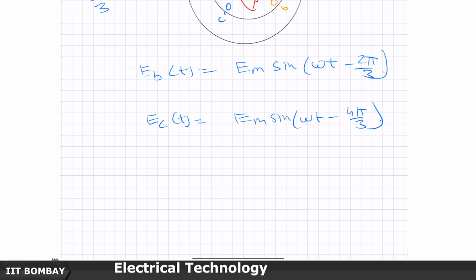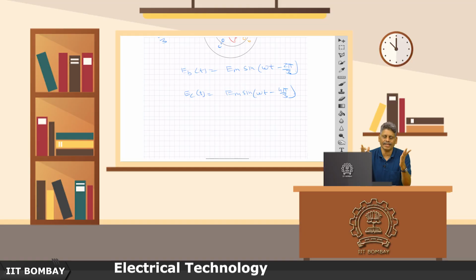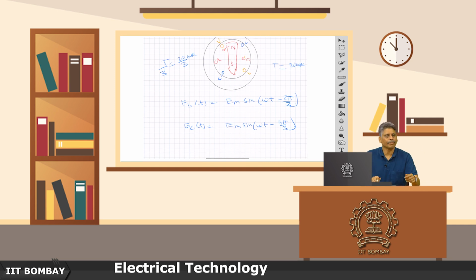Now, one thing is very clear: if I put a 3-phase winding, I will have better space utilization of my structure. So, going for multiple phases seems a good idea from the perspective of utilizing the space on the structure properly. There are more fundamental reasons than that, which we will come back to later.